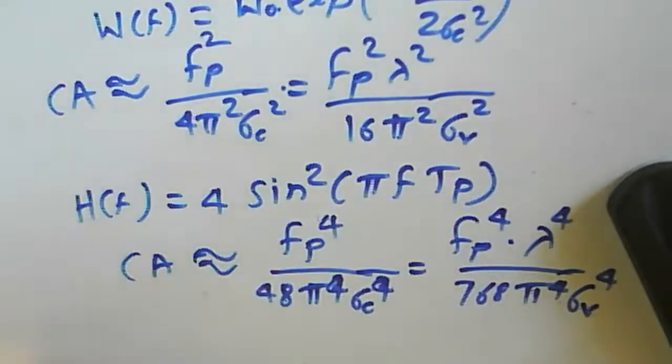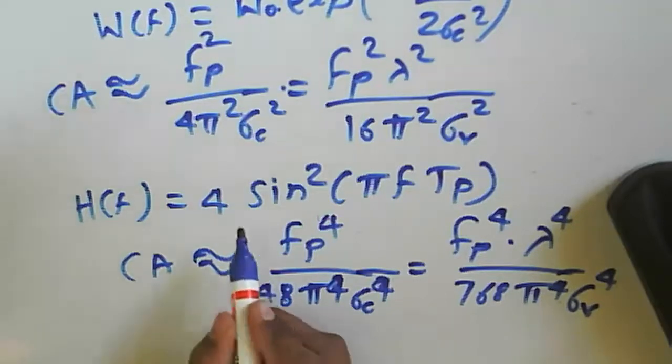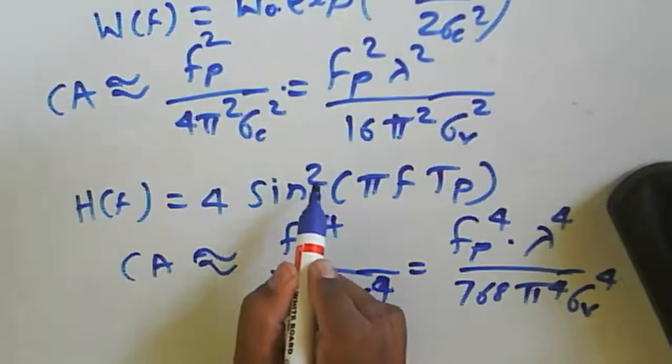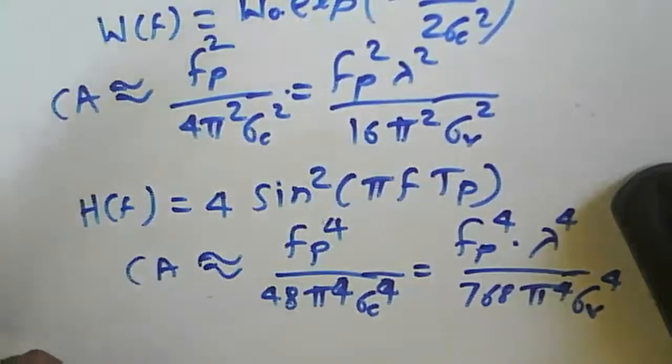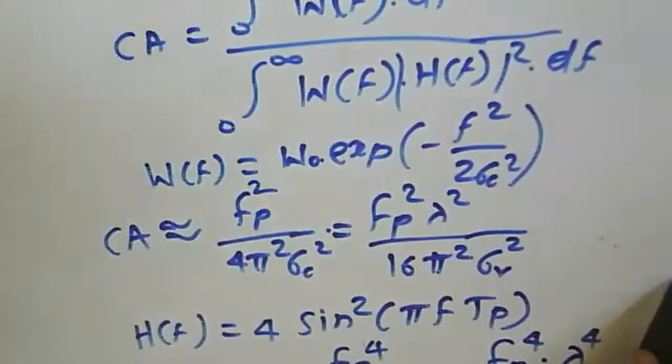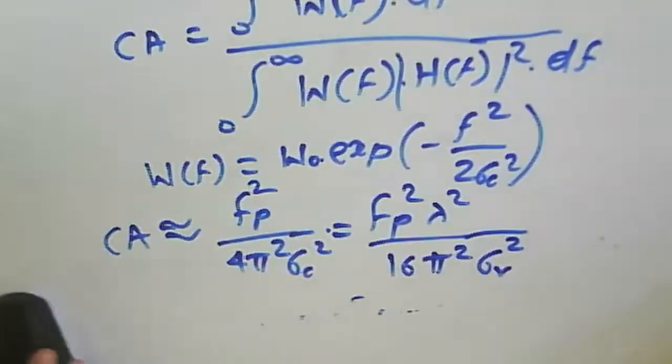Earlier, in the clutter attenuation equation we had twice sine pi f Tp. Instead of that, there will be 2 raised to n, sine raised to n, the nth power, for the delay line canceller. So we can use multiple delay line cancellers, two or n of them in cascade, instead of a single one, to attenuate the clutter information.